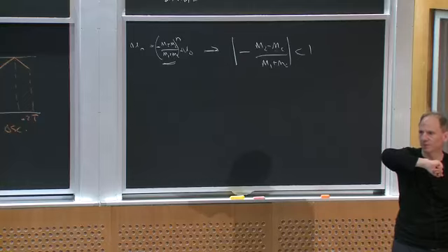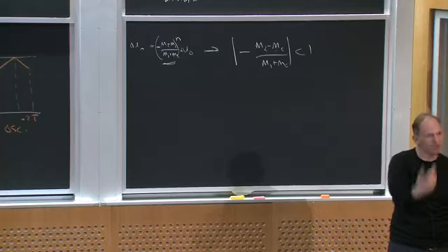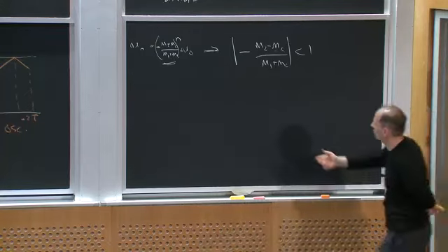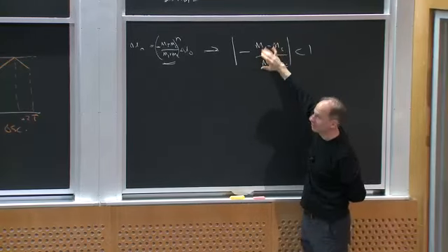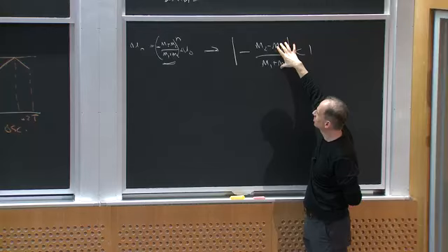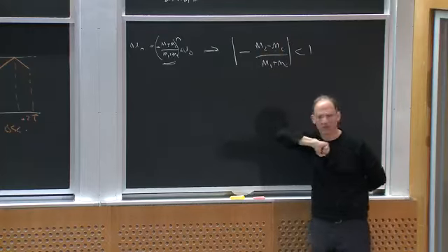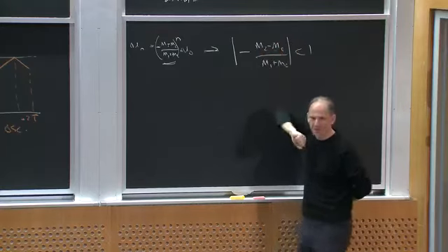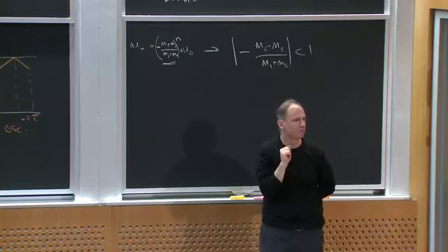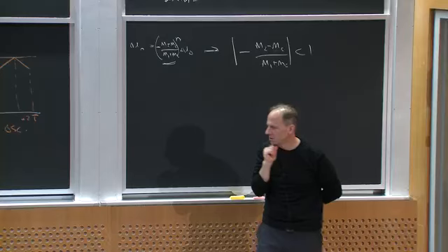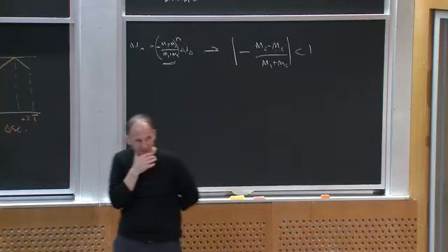Does that make sense to everybody? What M1 and M2 are depends on the converter, but we will pick this compensating ramp slope MC, a positive number, to be big enough that my ripple will decay away in a reasonable number of cycles. Maybe I make this magnitude less than 0.5 or 0.7 or something like that, so it'll settle down. Any questions about that?